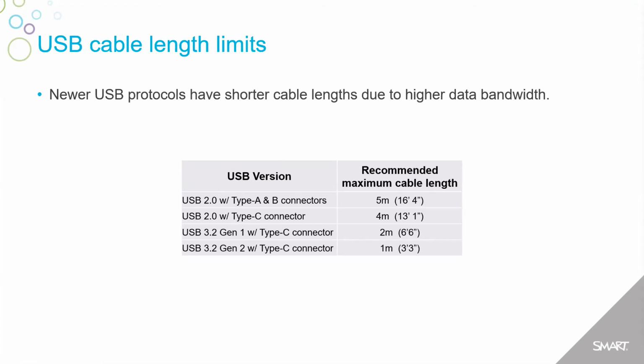If you're using higher resolution images, 4K 60, etc., shorter cables are recommended. And of course, that depends heavily on the cable itself, how it's manufactured, the quality of the materials within it, and so forth. Higher quality cables will obviously have better properties for resistance, capacitance, and attenuation, which means the signal can travel farther.